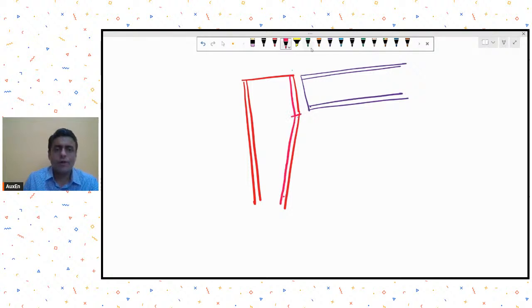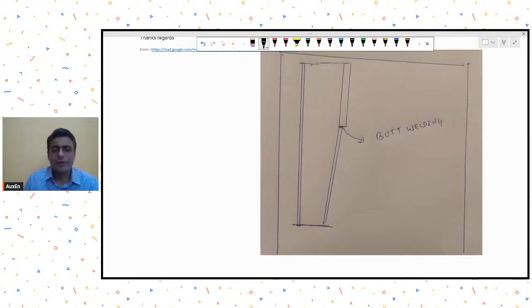Okay. Here, additionally, you will have to provide an extended end plate, and to this extended end plate your beam is connected, and then you will have your stiffener assembly, whatever, and then you will have your bolt assembly, whatever you are providing. So first thing, please understand that it will not be an abrupt situation like this, where you provide an assembly in which this is my end plate and there is no column flange.